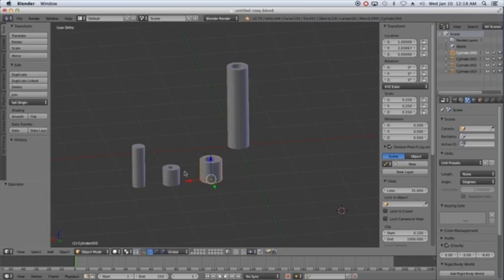This piece will be the little part that sticks up where you put a set screw to hold the prop in. And this is a 3mm cylinder that I'm going to use because we need to poke a couple more holes in these things. All right, I'm going to orient this with the origin in the center. This one has it on the bottom. If you want to change that, just highlight it, come over here to set origin, and go to origin to geometry, which puts it back in the center. This one for the top, I'm going to leave it on the bottom.